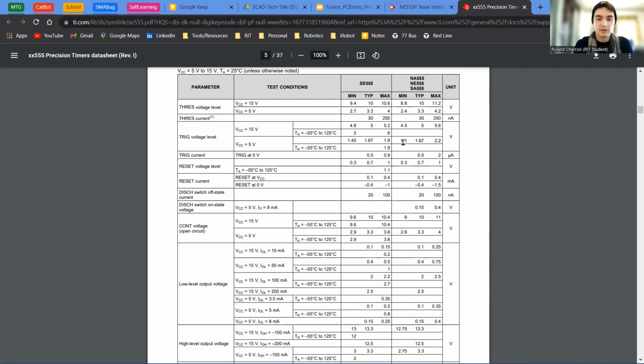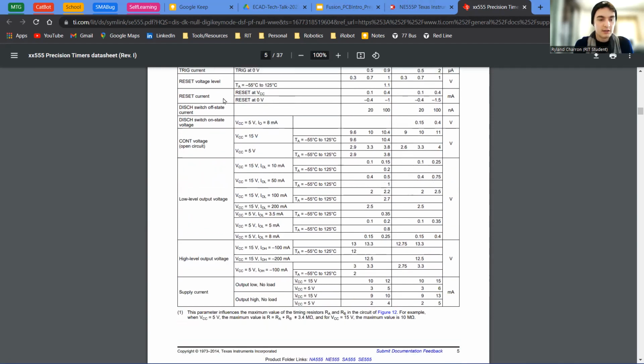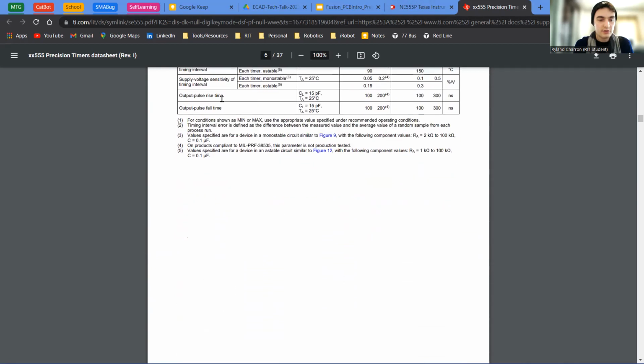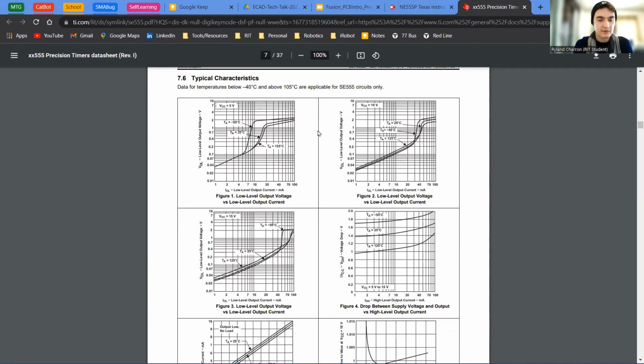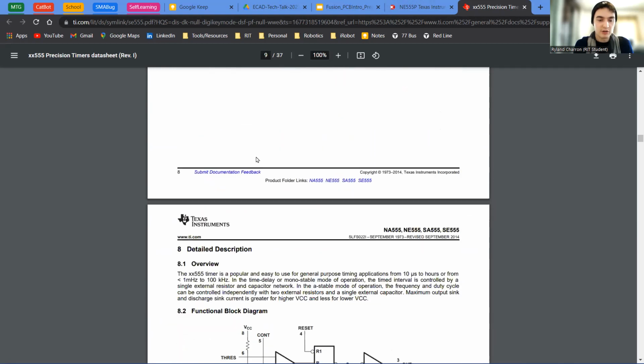We can work around this. It just means that whatever signal you're trying to put on this input pin, don't have it go much higher than 2.2 volts. And not more than half a microamp. Thermal characteristics, fun charts that I usually ignore unless something's broken.